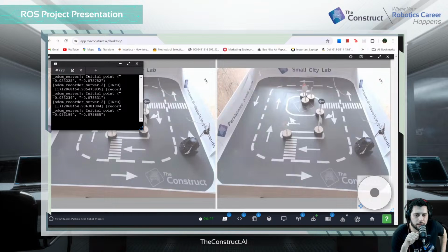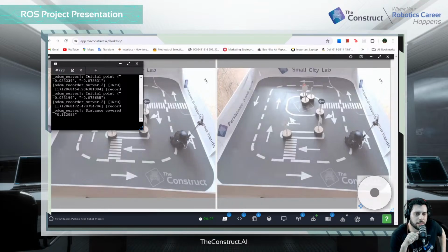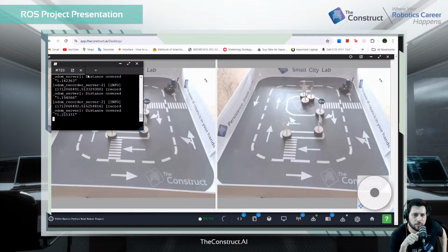Right. This is the wall finding function, where it basically finds the right wall and adjusts itself in the range of about 0.3 meters. It went backwards this time, and then it turns to the left to face the right direction, then starts the wall following node. It follows the wall in the range of 0.3 to 0.25 meters, using the right laser and the front laser, not exactly the front laser. I use the diagonal lasers to make it more concise.